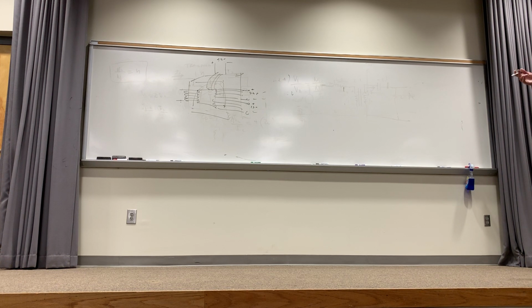Now the beautiful thing about focusing on the voltage is you'll never mess up the currents, because it's reflected impedance that gets it on the primary. Then once you get that primary voltage, the voltage in the secondary is either stepped up or stepped down by the turns ratio. Then you configure the current in the secondary without any kind of directional mess ups. All right, now we're basically done with transformers.